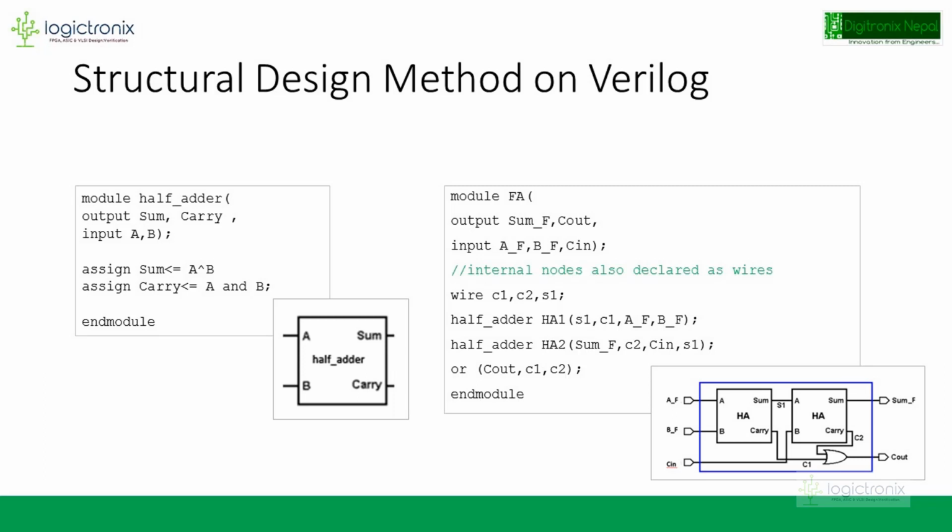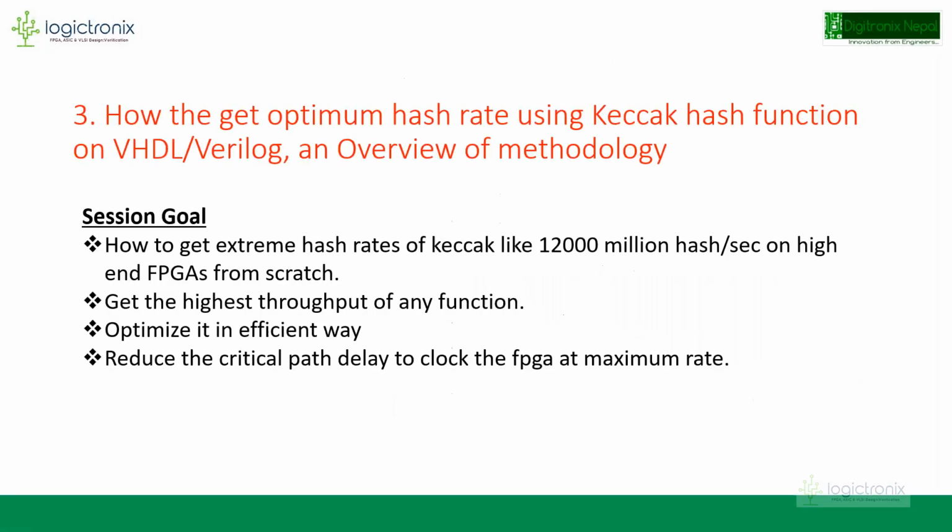So S1, C1 is passed through. These inputs of the full adder are passed through the half adder, and finally we can get the sum and carry. So sum is obtained from here and carry Cout is obtained from here. So this is the very basic block design. So this is the basics of structural design in Verilog. So let's go to the next one.